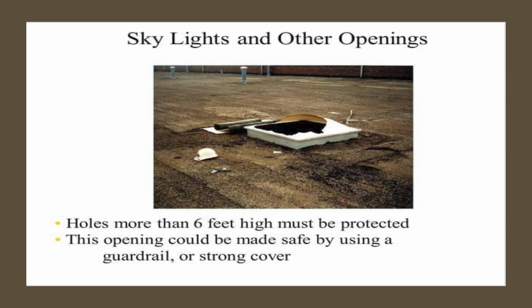Skylights and other openings. Holes more than 6 feet high must be protected. These openings could be made safe by using a guardrail or strong covers. Floor holes. Floor holes are another risk that costs lives in the construction industry. Cover completely and securely if any floor holes are identified. If no covers, then guard with guardrails. Never leave floor holes open and unguarded.